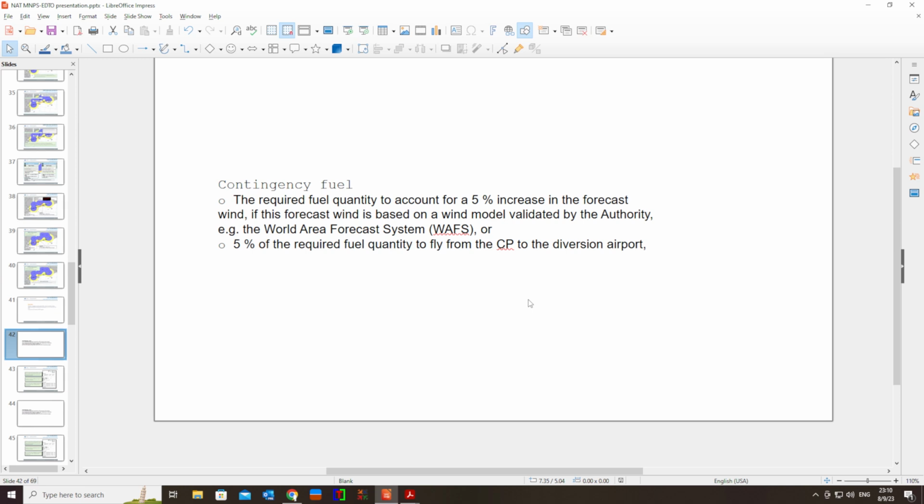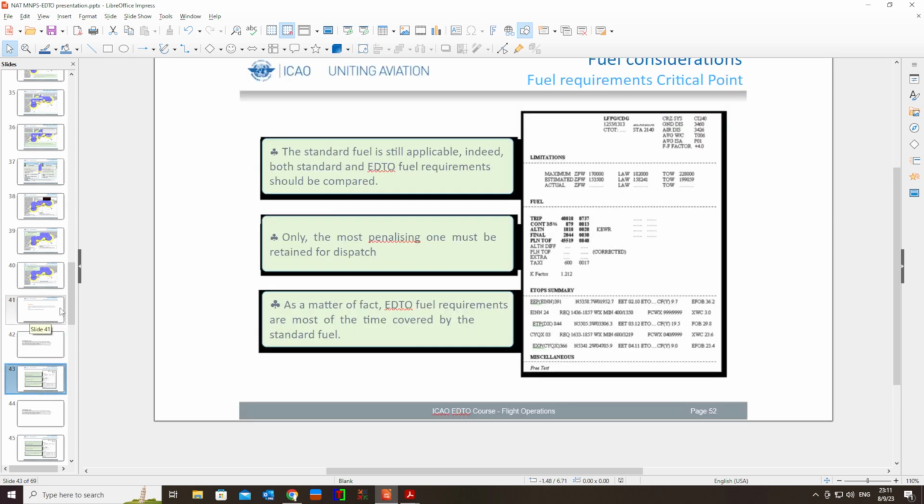If you use an ERA, en route alternate, extra alternate, the aircraft kind of reclears itself and you reduce your contingency fuel. We can go ahead and explain what the contingency fuel is and how we calculate it. I will create a presentation for that so that you know, but it's not the case for today's example.